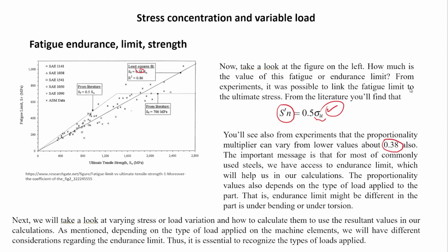Also, theoretically, the endurance limit is not going to be over 700 megapascals. So that's the top limit that you're going to find, according to theory. So to answer the question, what's the endurance of the material? Tell me the ultimate strength of that, and then I will multiply by 0.5, or divide it by 2, and then I will tell you the theoretical endurance of the material.